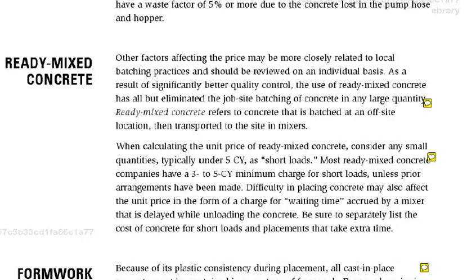In the same vein, when you're purchasing concrete, more and more we use ready-mix concrete. Why? Because it's made in a factory, in a plant, and so we can computer control the mix, the exact amount of stone, sand, water, cement. It's protected, it's done under managed conditions, and you can manage and control the transit mixer of the truck.